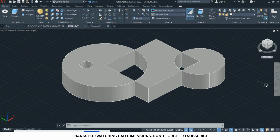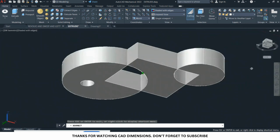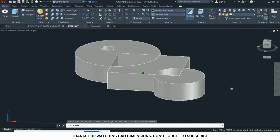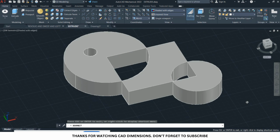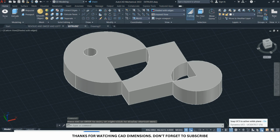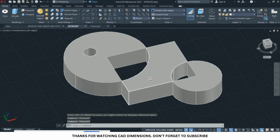So today we want to try and adopt using the navigation here instead of the mouse. Of course, the mouse increases efficiency, but yeah, this is the navigation. So you can see the hole that we have there. Now remember, if you want to draw on a particular surface, you need to make sure that your dynamic UCS is on. If you don't have it on, you can't draw on a particular surface. So you click on the customization, then make sure you have dynamic UCS on so that you'll be able to draw with respect to a surface.